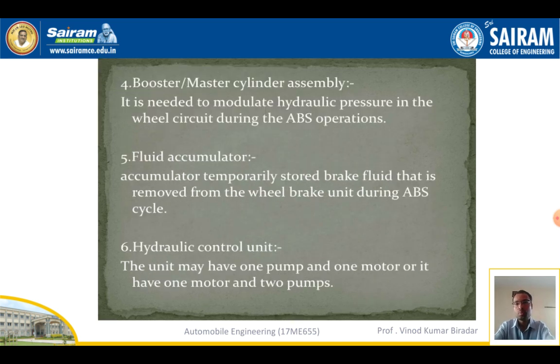Okay, so booster or master cylinder assembly. As I told you, the master cylinder is a very important part of any braking system. It is needed to modulate the hydraulic pressure in the wheel circuit during anti-lock braking. Next one is the fluid accumulator. The accumulator temporarily stores brake fluid that is removed from the wheel brake unit during the anti-lock braking system cycle.